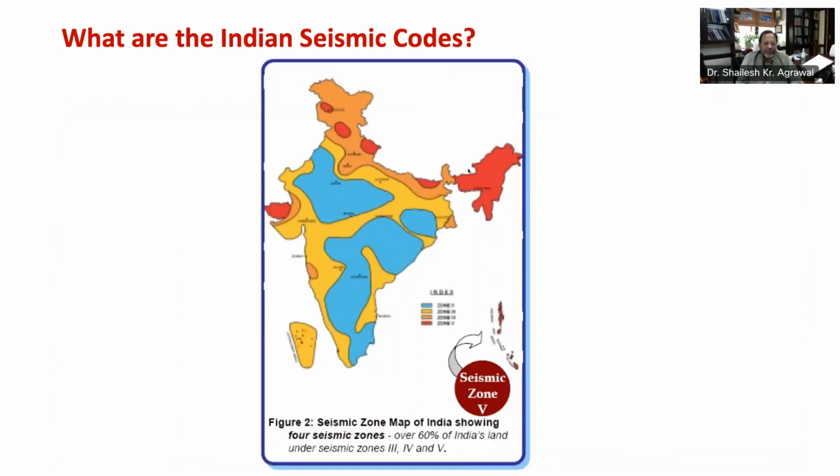This seismic coefficient depends on properties like seismic zones, which are shown in this graph, importance of the structure, its stiffness, and the soil on which it rests and its ductility. For example, a building in Bhuj, which falls in seismic zone 5, will have 2.25 times the seismic design force of an identical building in Mumbai, which falls in zone 3.